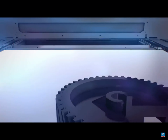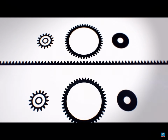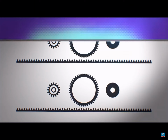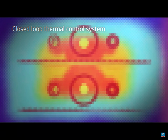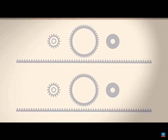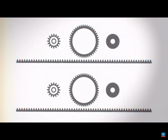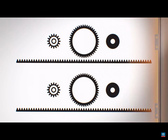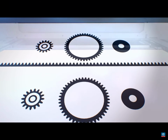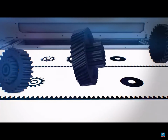The fusing process requires accurate temperature control across the entire material layer. HP Multi-Jet Fusion's closed-loop thermal control system does this by measuring temperatures at hundreds of points on the material bed. This information then determines which areas receive more energy to raise the temperature and which areas are cooled, allowing for control of thermal bleed and layer-to-layer fusing and cooling. The result is full control over mechanical properties, dimensional accuracy, and repeatability. The process is then repeated until a complete quality, truly functional part has been formed.